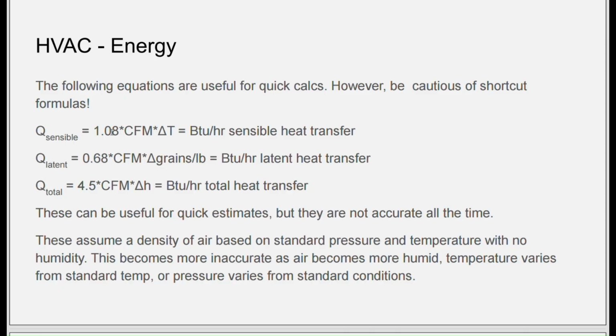The more humid you are and the further your temperatures are away from standard conditions, which is 68 F and 14.7 psi, the less accurate this equation is going to be. Typically, you're going to undershoot what your sensible heat actually is because this 1.08 should be a little bit higher to account for the water vapor that changes temperature in that process.